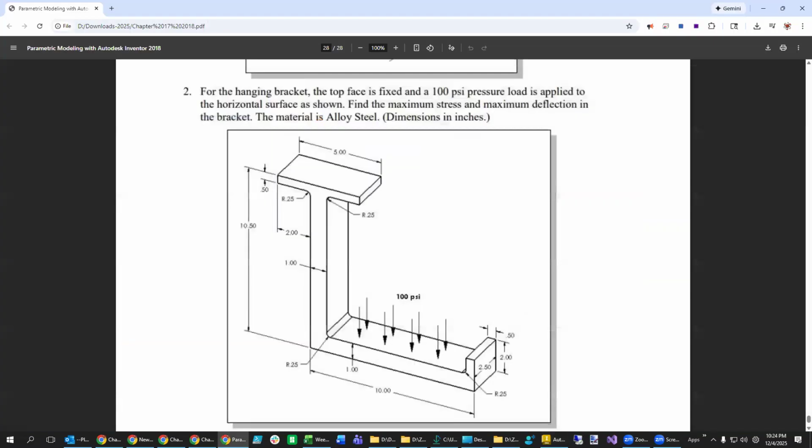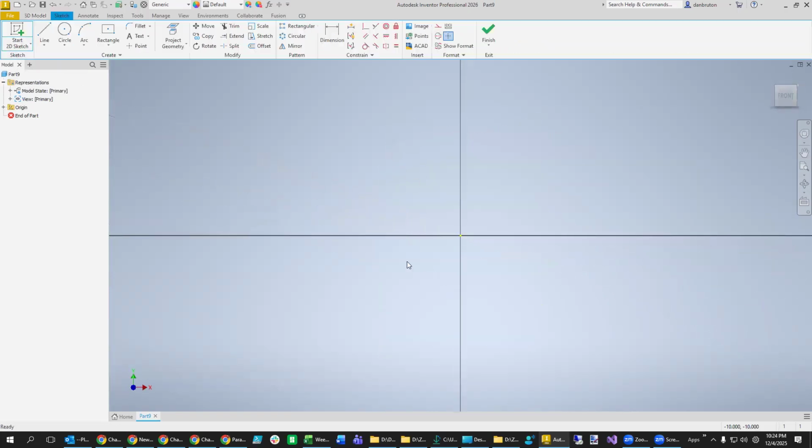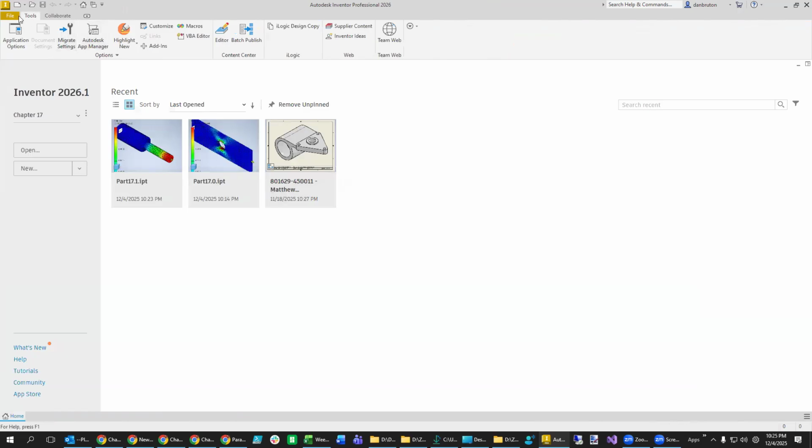One of the things I like to do is look at one of these dimensions and draw it first with the correct size, so that when it rescales, it doesn't cross lines from the freeform sketch. You'll see what I mean. I'm going to go over like this, and before I hit enter, I'm going to type in 10 for the 10 inches. Now it says millimeters there, so I must have clicked the wrong thing. You probably caught that in the video, so we're not going to save this one.